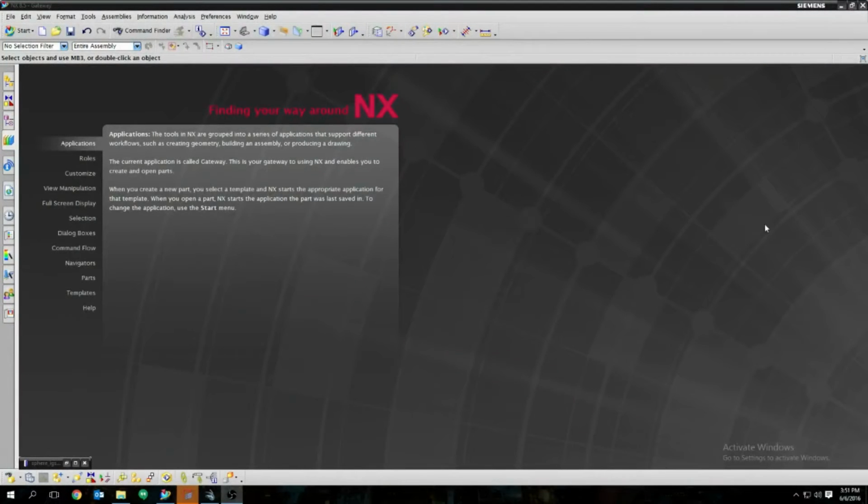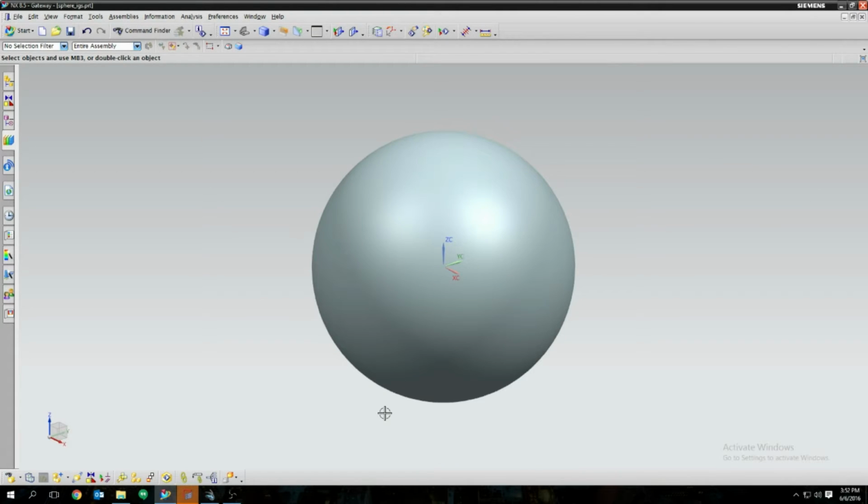For this video, we'll be covering how to do a fluid simulation using AcuSolve and Virtual Wind Tunnel, and solving the simulation using high-power computing. The first step is to generate the geometry. You can use any CAD software for this. In this case, we're using NX 8.5.